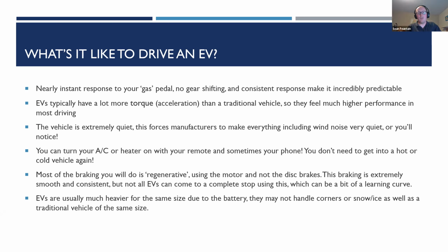One thing to consider with electric vehicles is because the batteries are really big compared to a gas vehicle, they're very heavy. They can weigh anywhere between 500 to sometimes almost 1,500 pounds more than a comparable sedan, for example. And they're on essentially the same wheels as the comparable gas vehicle. So there's the aspect of tires wearing out a fair bit faster with electric vehicles. But you pretty much never replace the brakes. So it often comes out as a wash there, if not a savings on your end. But the tires will wear out faster.